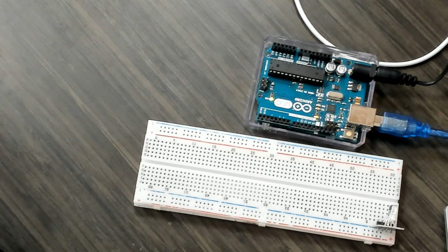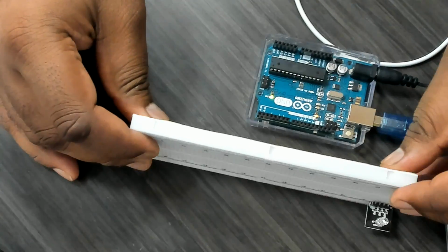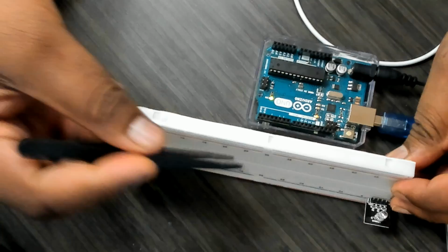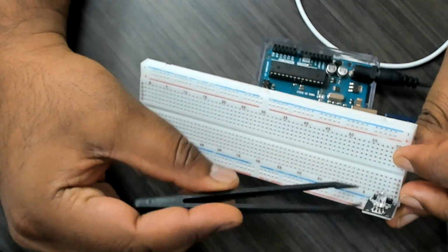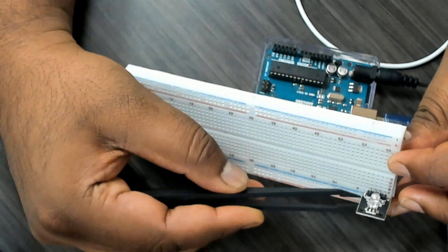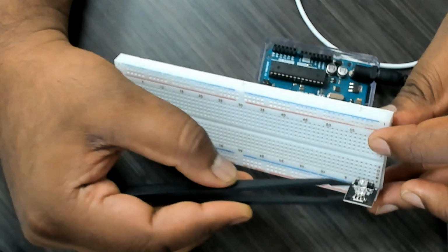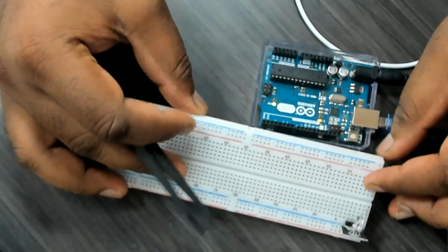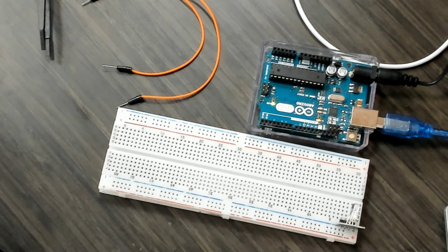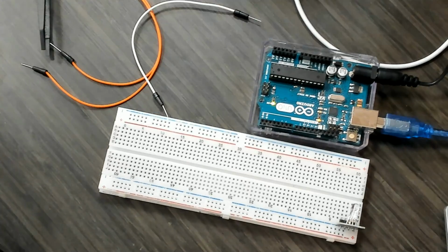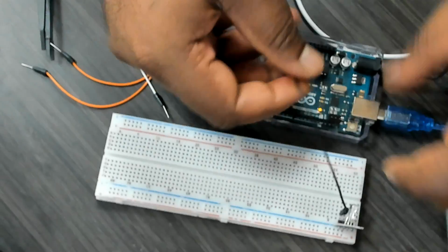So let me go to the board, and I have connected, I'm not sure if you can clearly see that. This is my unit, the module with the RGB, so it has the resistors. If you look closely, there are some SMD, surface mount components in there, like resistor components, so I just have to wire them. That is sufficient. So I'm taking 4 jumper wires, so let me place them here. Black I'm going to connect to the ground, so the last pin is the ground pin, so I'm going to take that and connect it to ground.